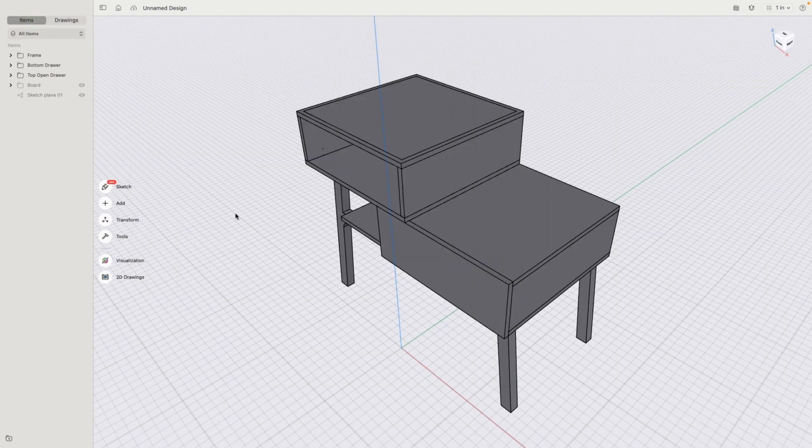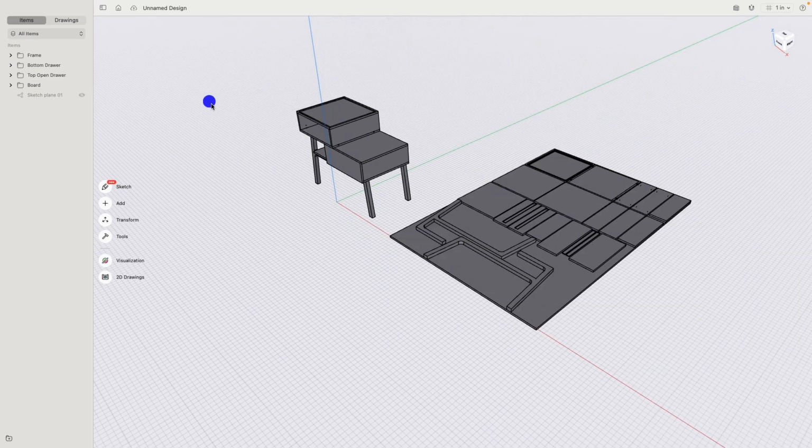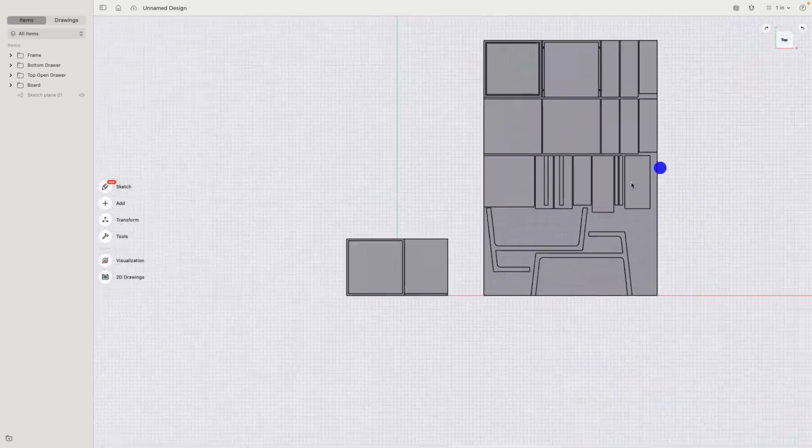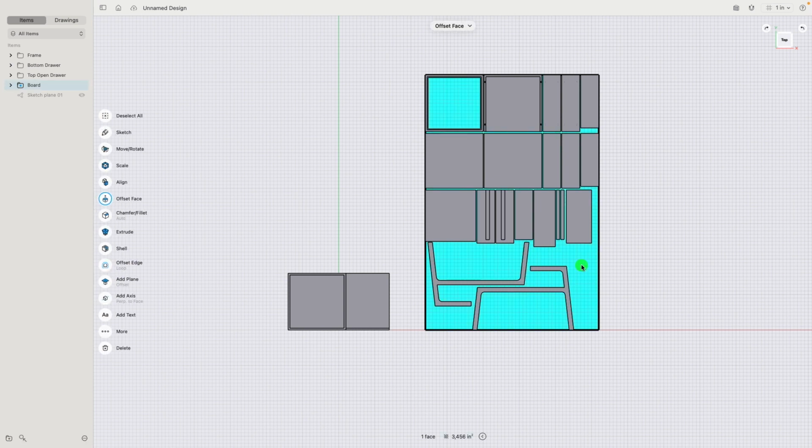One important aspect of mass production is also getting an understanding of the cost per unit and the raw material that's needed to produce one part. Also, this is very easy to do in Shapr. I have here a pre-made group. And if you take a look at this, this is a standard 4 feet by 6 feet wooden board, material thickness 1/2 inch, which is equal most of the elements we have. And I nicely nested everything onto this wooden board.